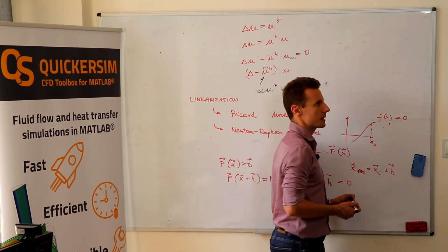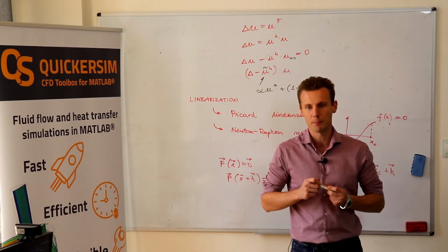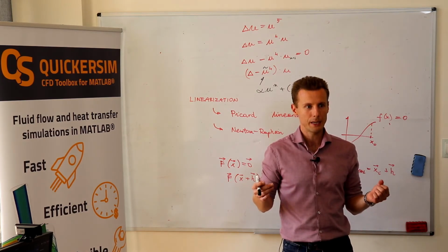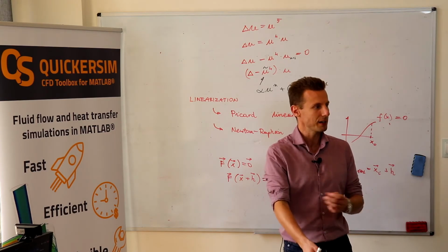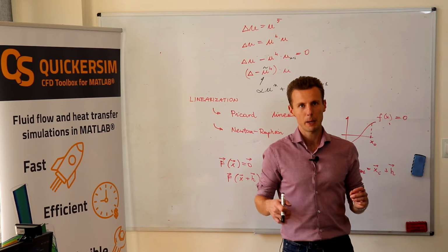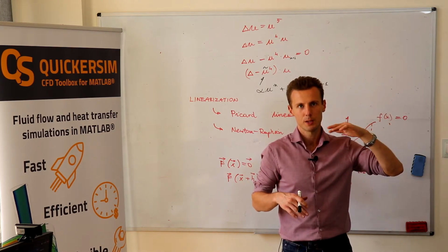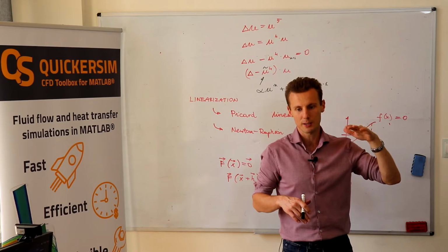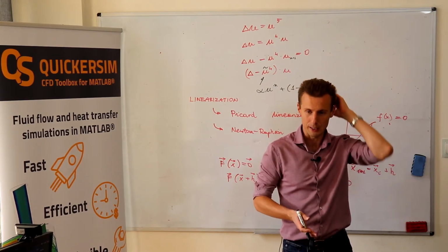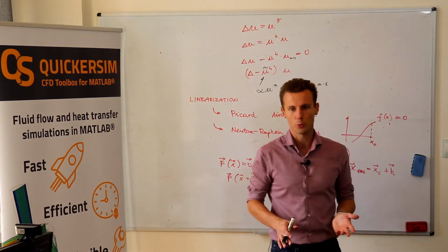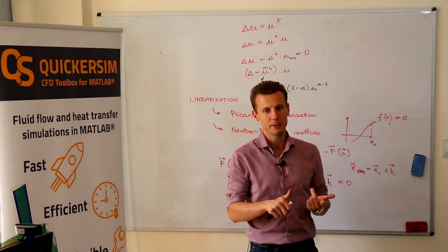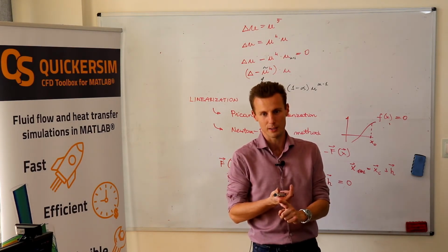The other case would be maybe not that problematic, but not very physical. It is if you've got a diffusion problem, so for example, a heat conduction problem, and you start convecting the flow. Imagine you've got some walls of temperature 20 degrees, you've got water at 0 degrees, you start convecting it, you know that for sure, whatever happens, your temperature values must be between 0 and 20 degrees.